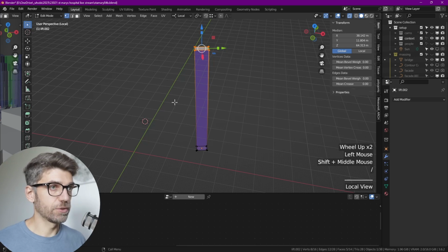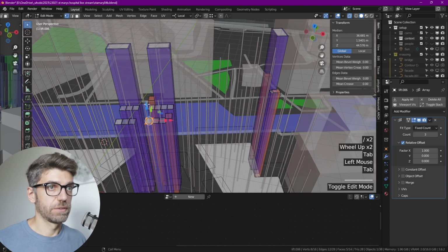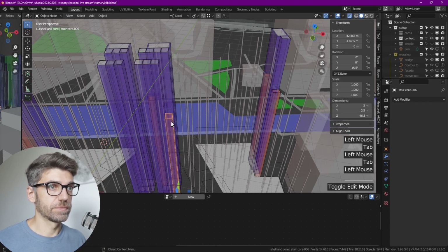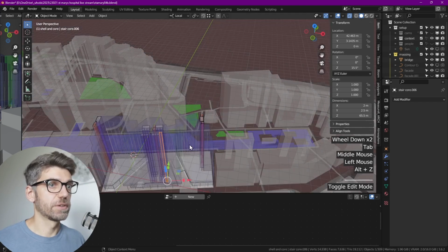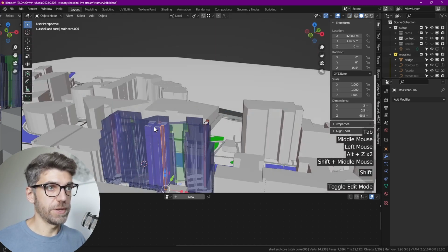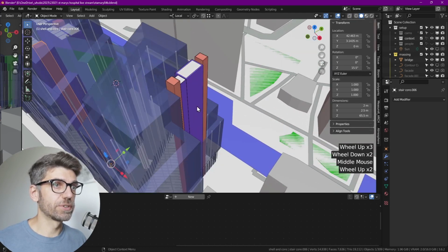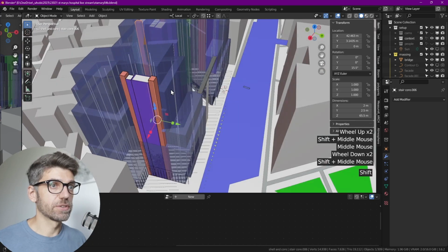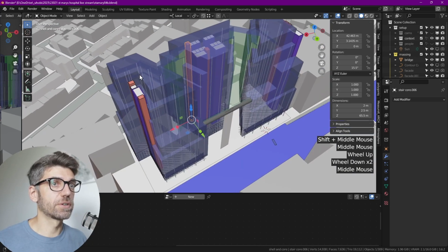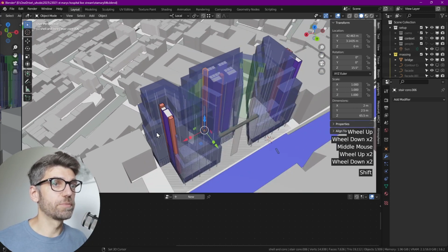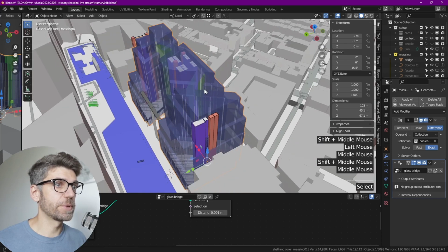How high do they need to go? Let's turn on the massing again, just to see. I think they need to go a little bit higher. So we got three elements here. Okay. And now we have an issue. That setback here doesn't work because the core then is not really working with it. So we either need to move this core to be a little bit further inside or that setback is moved back. So for now, those setbacks are going to be canceled.